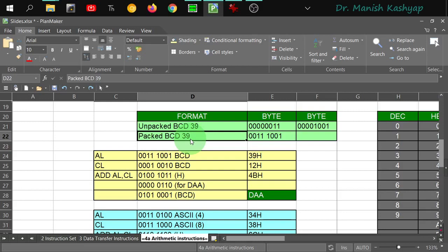And here you are essentially putting information of 2 digits into one number, that is 3 and 9. So that is why we say that we have packed two numbers into this 1 byte. So this is called packed BCD.